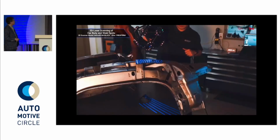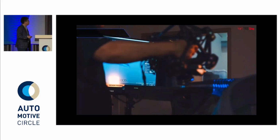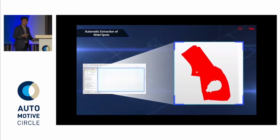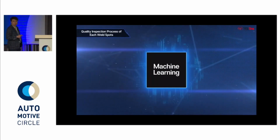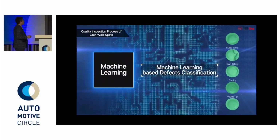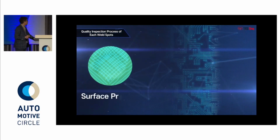Okay. If you have any component, we can do this manual scanning. Also, it can be scanned by the pre-teach robot, and each spot of the scanning data for the component can be extracted automatically. And then with machine learning technology, we can classify more than 7 different types of surface defects.